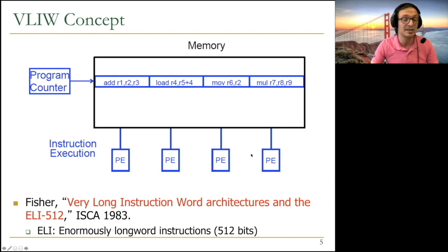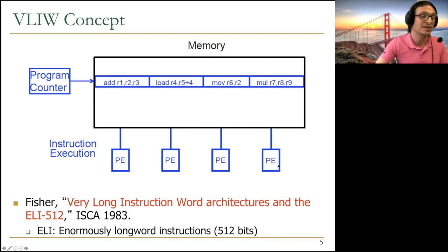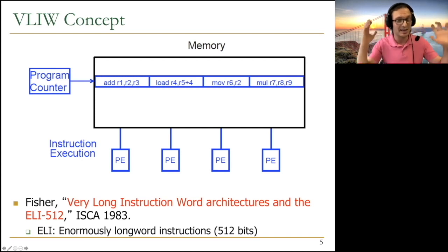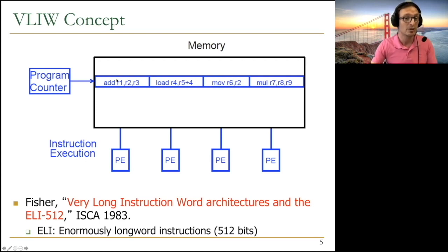Basically, in the traditional VLIW, the compiler needs to have a very good view of what the hardware looks like, where exactly each processing element is, such that it packs the instructions in a nice way, such that the hardware doesn't need to route the instruction to the correct processing element that can execute it. This is another example of the philosophy, which we will get to. Basically, hardware stays as simple as possible. It doesn't even provide the network or the connectivity to take this instruction to this adder over here.